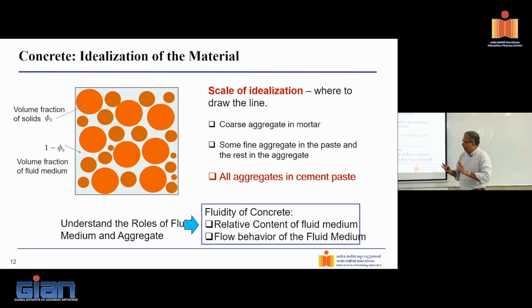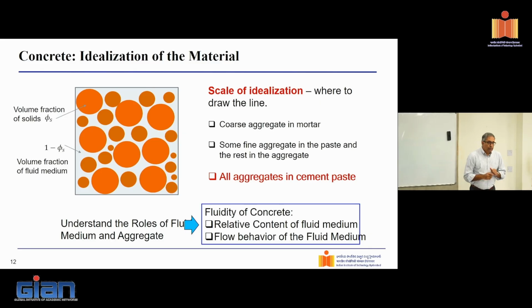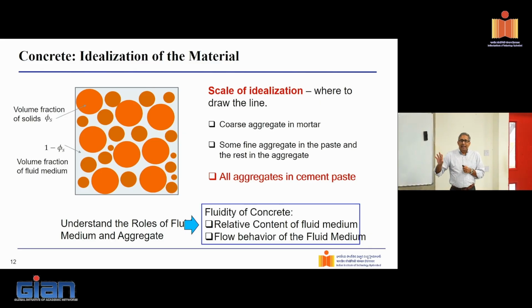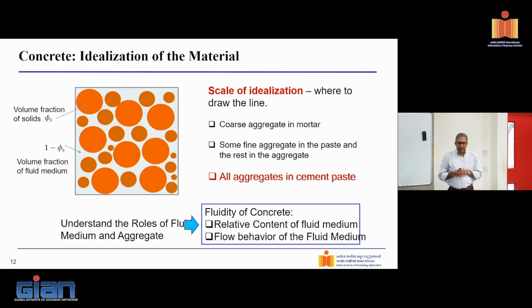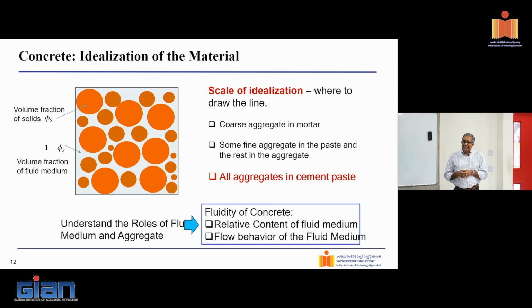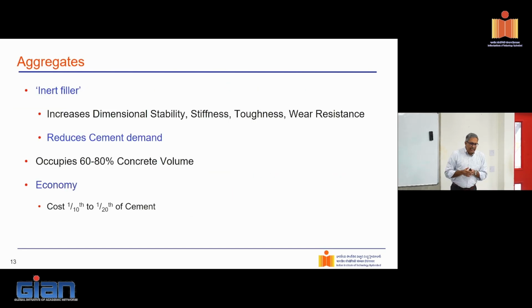Okay. Now, I'm interested in controlling the flow behavior and also trying to adjust the relative content of fluid in this solid medium, and this becomes important. The relative content of the fluid medium, the relative content of the paste, becomes important from an economy perspective, because I want to minimize my cement paste in the concrete, right? Now, so let's look at the aggregate.